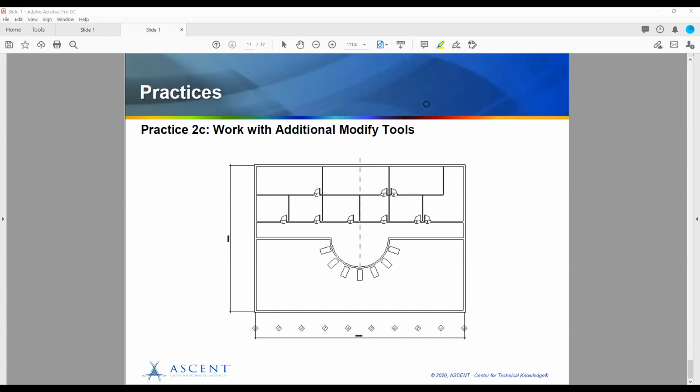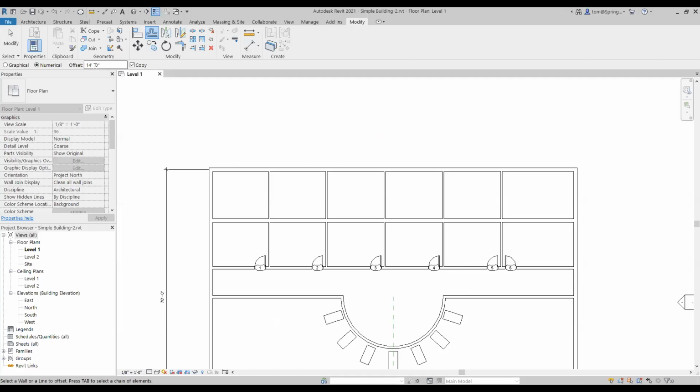While I'm still in the offset command, I'm going to change my offset distance up here to 10 feet. So I change it to 10 and hit my enter key. Then I'm going to offset this last vertical wall over to the side like this. I want it to go to the right, not to the left. So I'll click here and make sure it's there. Boom, I'll click there, and it offsets it over there. So we're good to go there.